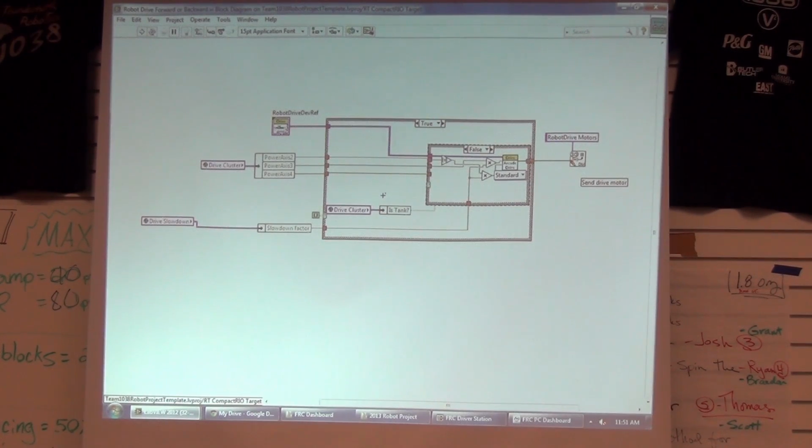And we have it set up so if the driver pushes a button, this is also from events, it's also another part of pulling on the joystick. If the driver pushes a button for tank drive, it would flip and use the tank drive VI, and then when they want arcade, they can just flip again. Then, after those go in there, the drive value goes into the reference, which it now knows because of Begin. This is the same thing from Begin. It knows where the motor is, and then it drives. That's how it drives. This little extra thing over here is part of network tables.